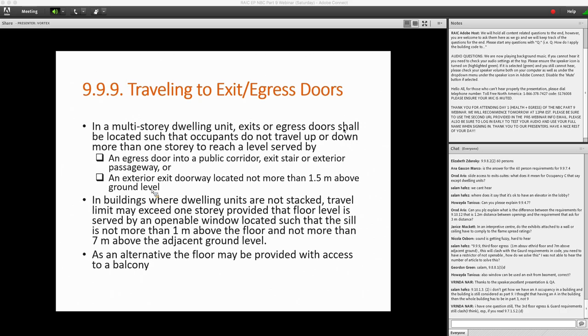So under Part 9 it talks about party walls, that is party walls that are required to be 1 hour, but firewalls required to be 2 hour is actually discussed in 3.1.10 of the code. So if you go to 3.1.10 of the code,